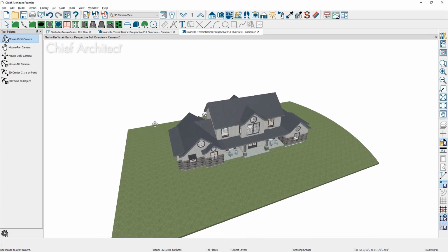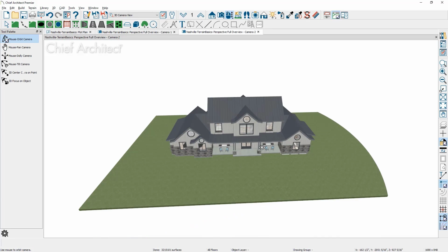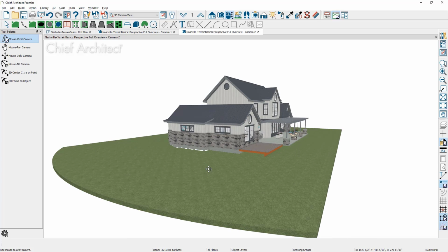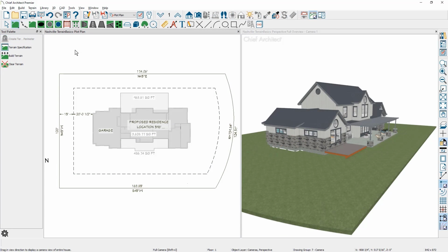In this view, you can see the terrain has come in flat. On the right hand side of the house, I want to create a slope where the terrain will slope away and allow the pier style foundation to be supported above the slope on that terrain. To create this slope, let me tile my screen by pressing Shift F6 on my keyboard.